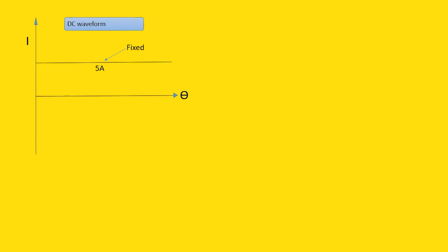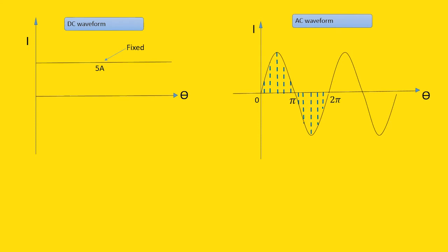Now, before we see what is an RMS value, we need to know the need for RMS value. We see that for DC waveform, the values are fixed at all instances for any quantity, while in the case for AC, the values keep changing at every instant. So we require a fixed value which can be used to refer the quantities in general, like 10 volt of voltage and 3 amperes of current, which should imply the values are fixed. In other words, we need a fixed value which is a DC equivalent of the AC quantity.